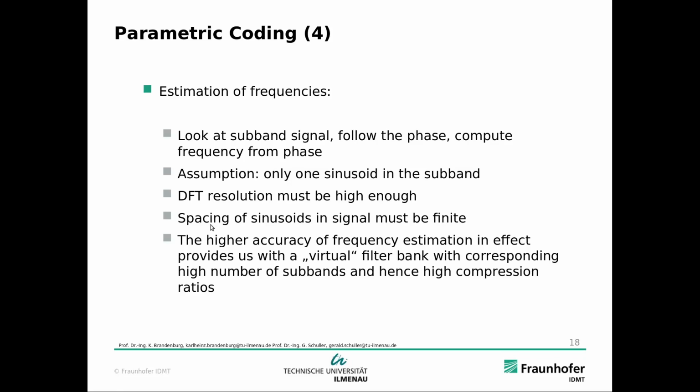Yeah, and also that means the spacing of the sinusoids in the signal must be finite. So we cannot have a noise-like signal, right? There we would have infinitely many sinusoids. So the higher accuracy of frequency estimation in effect provides us with a virtual filter bank with a correspondingly high number of subbands and hence high compression ratios, right?